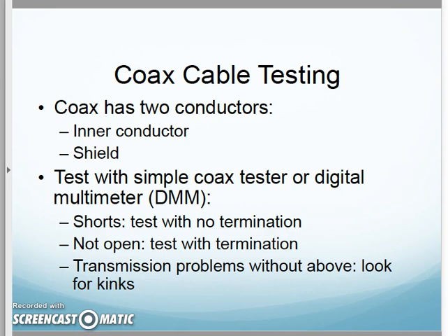If you're installing video cabling, coax cabling for any reason, after it's installed, you obviously need to test it. They give us two options here. They tell us we can test with a multimeter. Absolutely. If I use a multimeter, I can test the center conductor from end to end, and then I can test the insulation or the shielding end to end and make sure there's no shorts or anything of that nature.